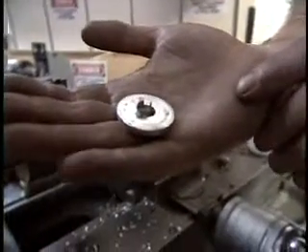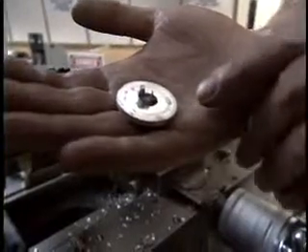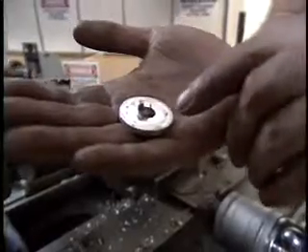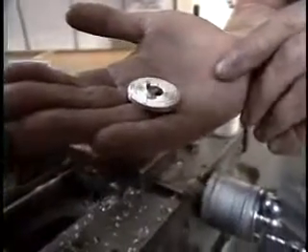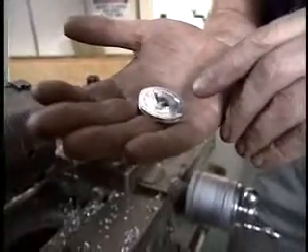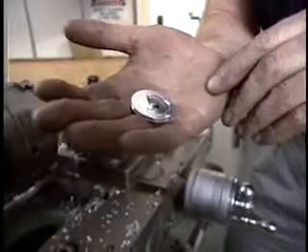You can see here the finish of the cut. About halfway down, you can see that the cut is a little rough and not as shiny. That's the part of the cut where I was not using cutting fluid. It's very clear from this the benefits of using some cutting fluid while you're using the cutoff tool.